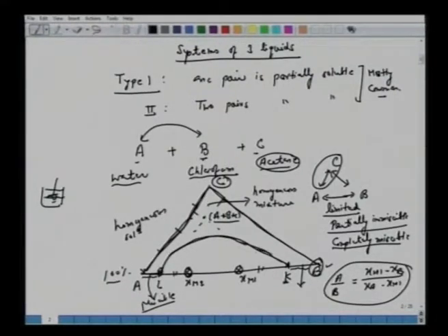For the ternary system A, B and C, we have a homogeneous solution mixture in this range. If you hatch it like this, and if we now choose a component or a mixture here of A plus B plus C within this region and allow them to stir, now you will see a separation like this. There will be two phases. One phase will contain the amount given by these coordinates, and another phase will contain the weight fraction of C given by this coordinate. So here we are talking of this phase separation.